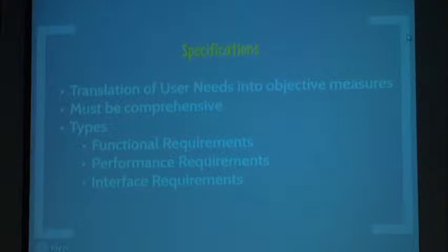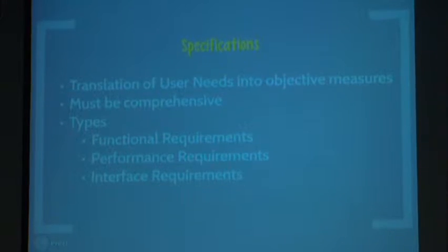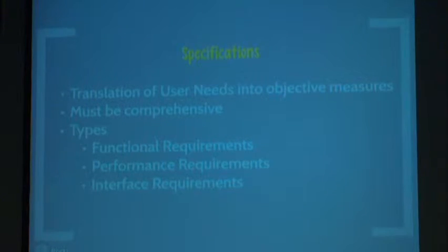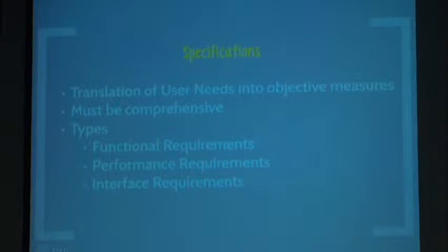Primary features of a product. Sound good? So specification, you're taking one of those primary features and you're giving it quantitative measures. So you're wanting to say, how can we specify what this is in a quantitative way and be able to make that translation. So this is what you're going to measure yourself against after you design, okay? So when you go to do verification at the end of your design and you're testing a design, you're going to test against your specifications.